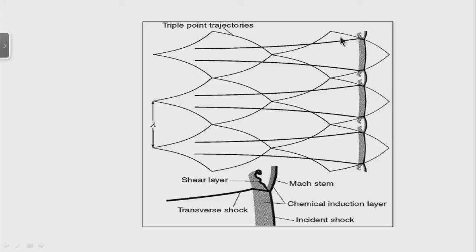That means if a transverse wave rebounds at the wall and comes back, well and good, but if one transverse wave hits against the wall and the second transverse wave is also hitting against the wall, and I have something like 3 or 4 transverse waves formed, then I cannot really maintain the continuity, because I cannot energize these transverse waves and have them hit at the triple point intersection.